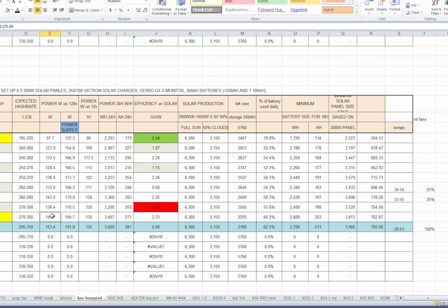So just to be safe, you should use a little bit of extra power there. 80% is what's recommended, to the maximum. I mean, if you do like 82%, it's probably not gonna burn the PSU, but I wouldn't recommend it. It's always better to have extra power than less, because otherwise it's gonna overheat your PSU or give extra heat that you don't need, especially in an environment where you can't cool it down. Let's say you're in a garage where you already have 90-degree temperature, then it's gonna really hurt that power supply.